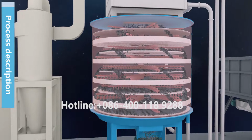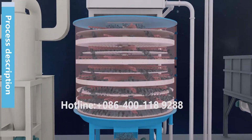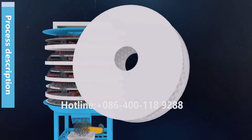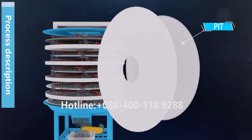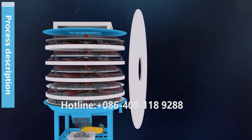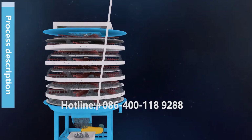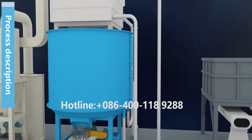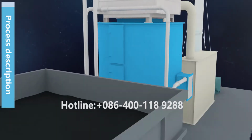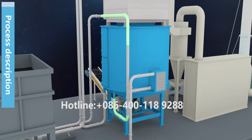The surface and back plates of the disc with pressed pits are usually welded manually. However, our plates are pressed by numerical machine, and the disc is gap-free welded automatically with high electric voltage. There is no leakage or corrosion at the welding points, providing the necessary conditions for long-term operational life. A qualified trap is used to prevent steam leakage, and the condensed water is recycled to the boiler or other heat consumption unit.